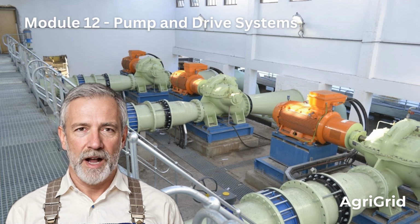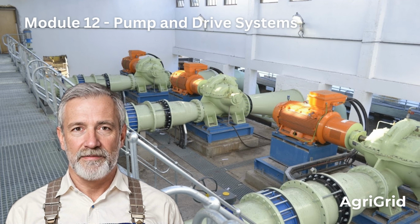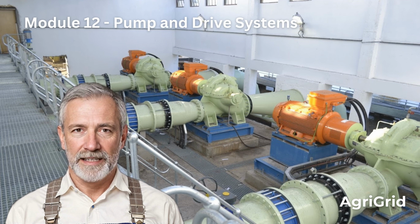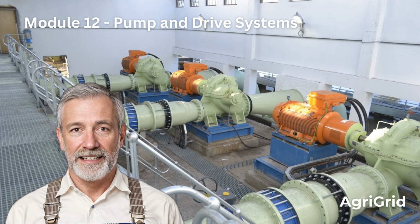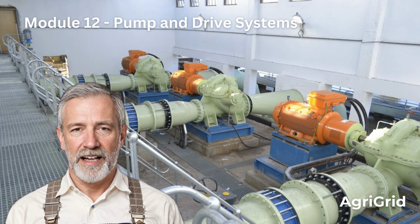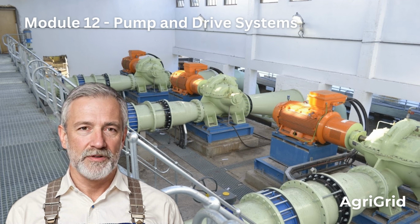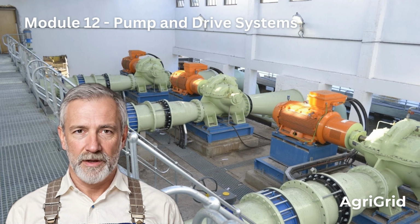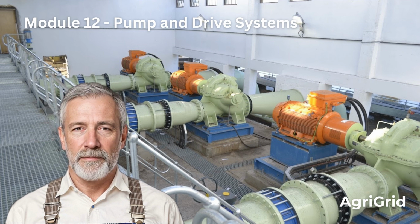We will then examine the array of pump technologies available, classifying them based on their operating principles, design features, and applications. This classification will encompass positive displacement pumps, such as gear, piston, and diaphragm pumps, as well as dynamic pumps, including centrifugal and axial flow pumps. To equip you with the necessary skills to assess pump performance effectively, we will introduce you to a range of tools and techniques. These will include methods for measuring flow rates, pressure differentials, and power consumption, enabling you to optimize pump selection and system design.